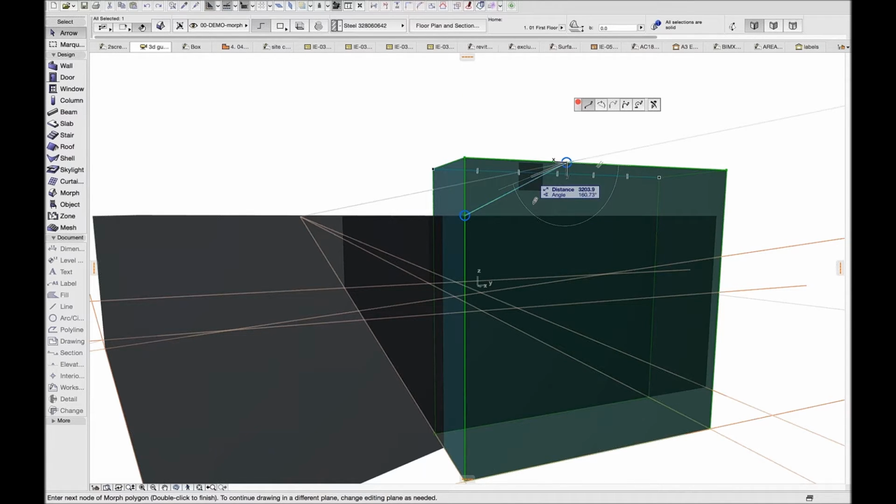In this example, we trace the intersection point of a horizontal and vertical line. We pick up the previously created morph line segment's direction and use it to draw the next ones. So using now the parallel lines offered by the snap guide.